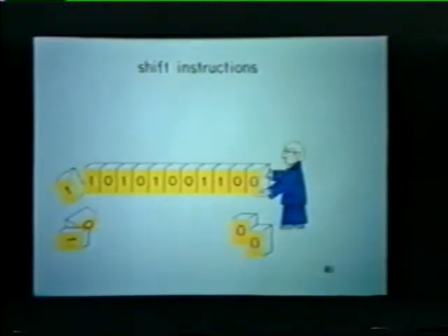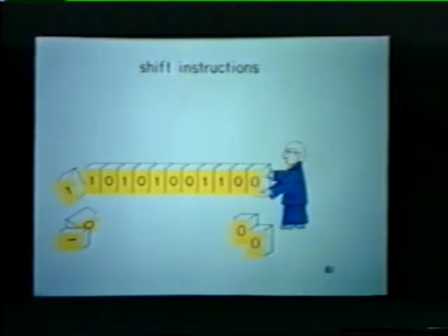Although the shift instructions ASL and ASR are very useful, they do have one disadvantage. As we shift left, for instance, we keep adding zeros to the number. However, the bits shifted out of the word are lost completely. Suppose we didn't want to lose these bits. What could we do? One solution would be to construct a circular buffer so that a bit shifted out of the left side of the word would rotate around and enter the right side of the word. Thus, we would continually shift the bits without ever losing a single one.